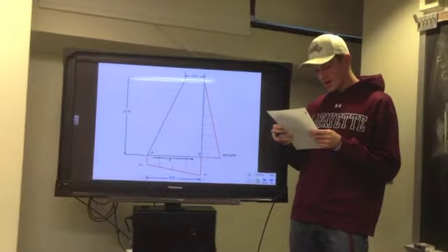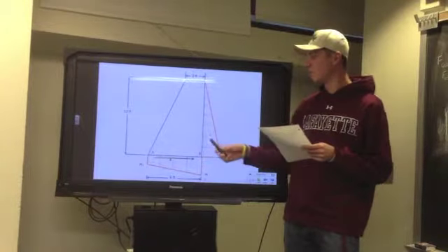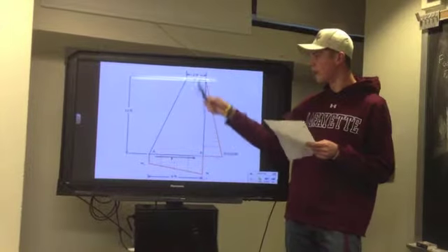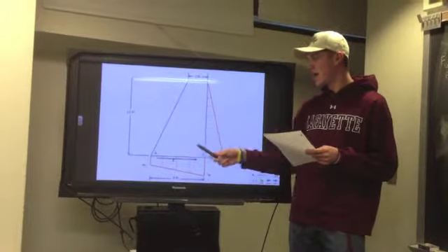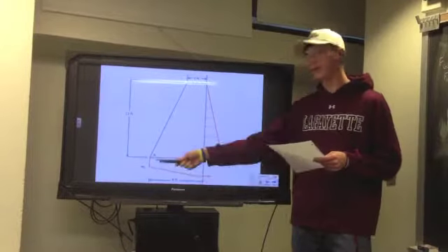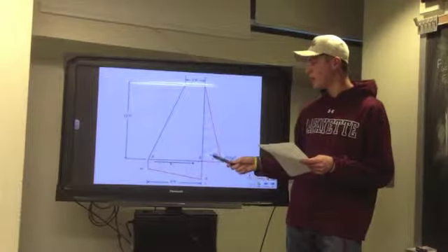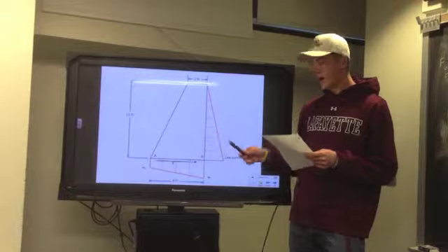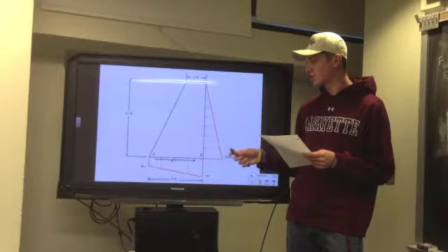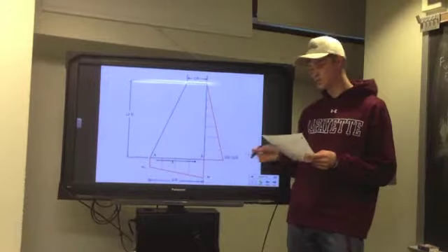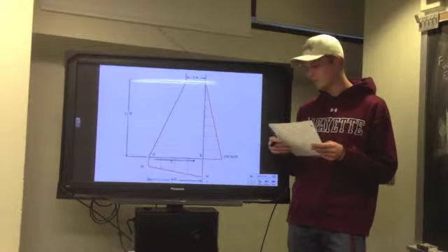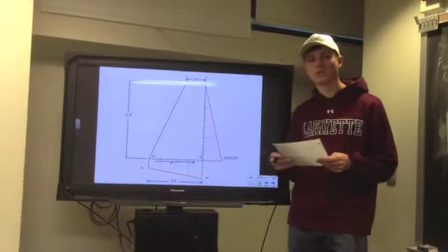And then you can break the concrete retaining wall into two equal parts, so you can have the rectangular side over here and the triangular side. Since we still have two unknowns left in W1 and W2, getting the sum of the forces in the y direction and getting the moment around point B will give you two equations, and then with two unknowns you can solve for F, W1, and W2.